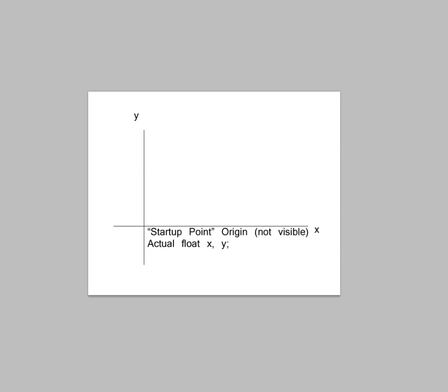When that happens, the program has a hard time determining when 2 walls are exactly perpendicular to each other, and this can cause some rather frustratingly bizarre behavior. For instance, ever so slightly changing the angle between 2 lines without you knowing it, when all you wanted to do was to change their lengths, and other strangenesses. Revit will warn you when it detects that a line is almost but not quite exactly horizontal or vertical for precisely this reason. So it's best to draw your building orthogonally to this system by drawing orthogonally to project north.